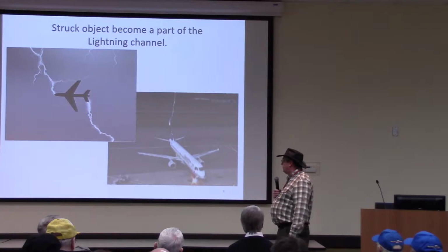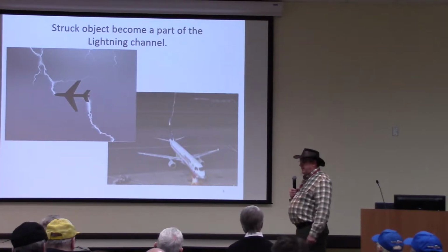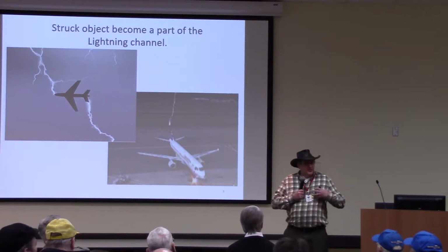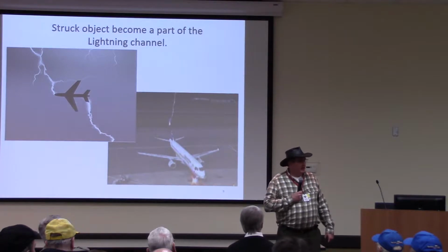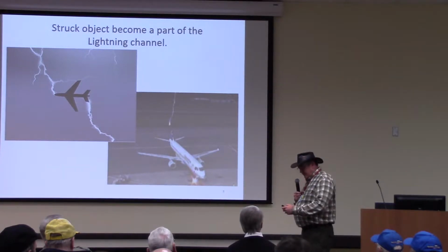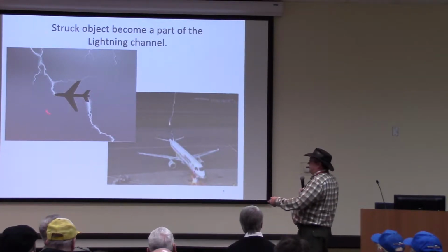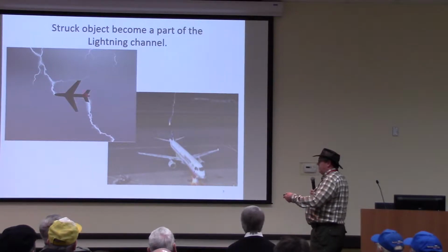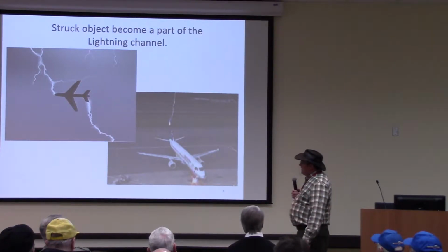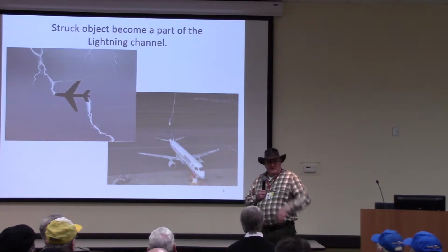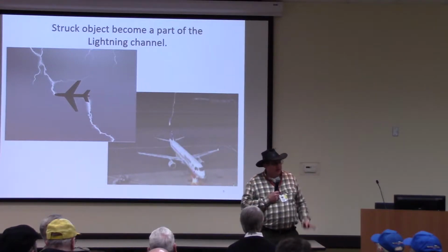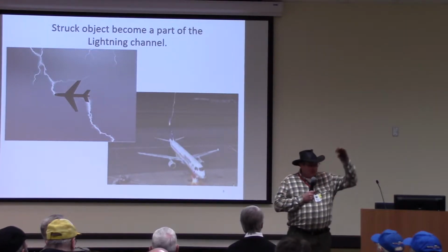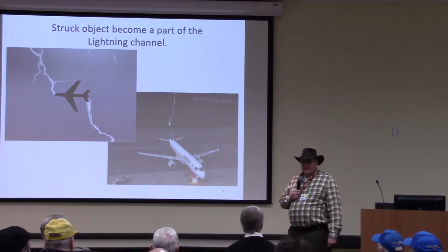But the main protection for metal aircraft is to try to keep all the currents distributed onto the skin of the aircraft on the outside of it. You can get struck in flight. Matter of fact, this is when most aircraft are struck, in flight, probably right around the 10,000 foot level, right before the cloud deck, either when they're ascending or descending.